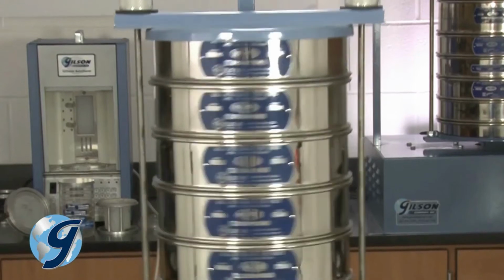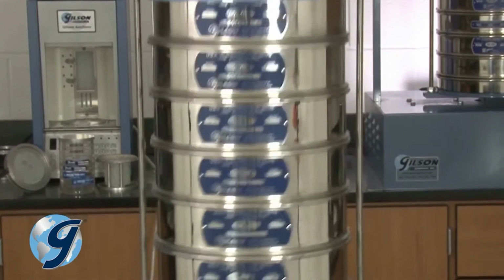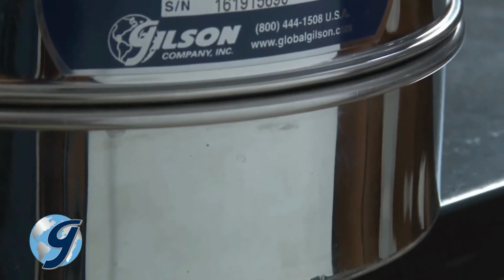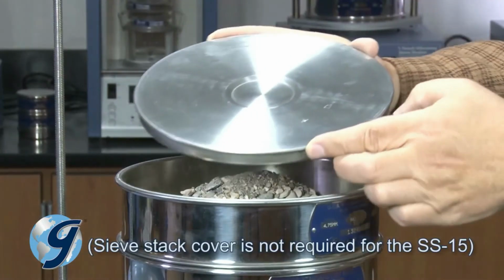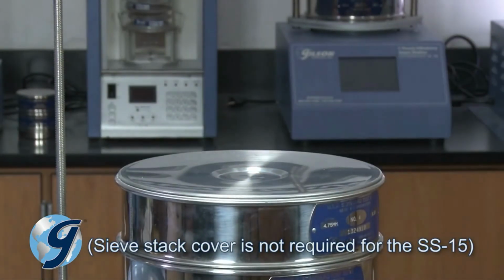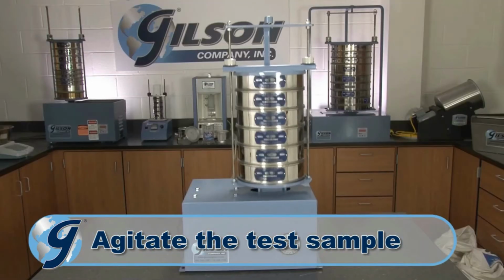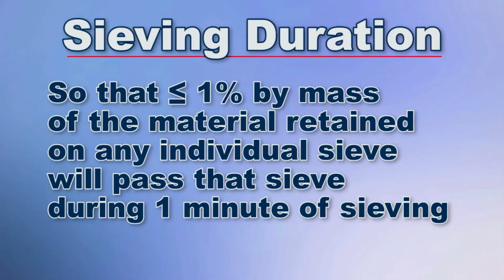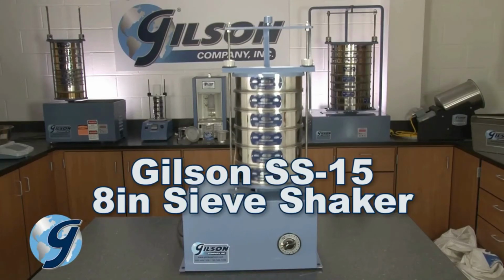Today, we're using Gilson 8-inch ASTM E11 stainless steel compliance grade test sieves. Place the sieve stack onto a sieve pan. Now place the test sample onto the top sieve and then cap the sieve stack with a sieve cover. Agitate the sieves by means of a mechanical sieving apparatus for a sufficient period of time so that not more than 1% by mass of the material retained on any individual sieve will pass that sieve during 1 minute of continuous sieving. For this demonstration, we are using the Gilson SS15 mechanical sieve shaker.